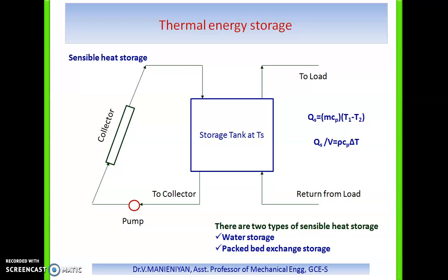For many domestic applications, storage systems such as water or rock have evolved. Water and rock are typical examples of materials which store energy as sensible heat, but they are limited by their comparatively low specific heat. The heat of fusion, which is a latent heat involved when a substance changes state from solid to liquid, provides an attractive method of storing energy.